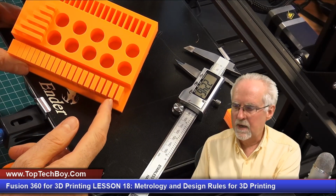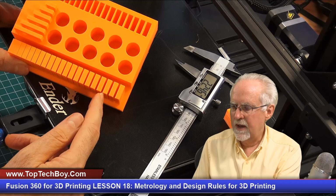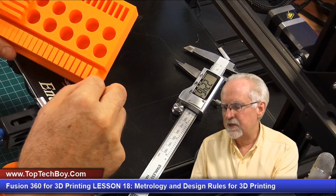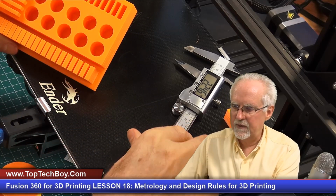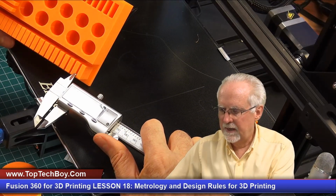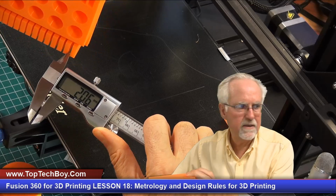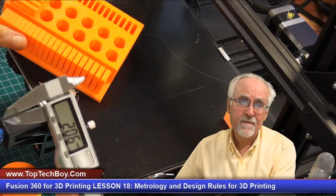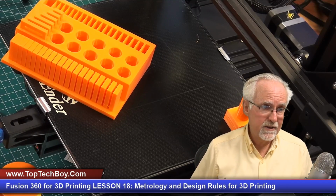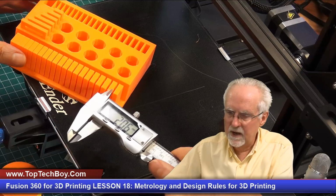So if you look here, I started by creating a 2 millimeter gap. That looks great. A 1.9, 1.8, 1.7, 1.6, smaller and smaller gaps. So let's start here and see how precisely we got this gap that we wanted to be 2 millimeters. This is actually kind of a hard measurement to make. You can see 2.06, again that theme that we're seeing of a precision in the X and Y axis of about 0.05 millimeters.